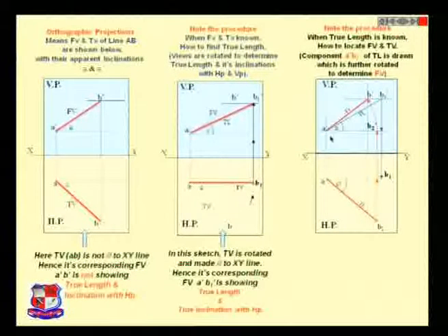Now from the true length, from this true length of the vertical plane B1 dash, I have dropped down the shadow till B1, and with AB1 as radius, A as center, mark an arc which in any case will cut the B point, which would be on the B2 parallel line itself. Join the line and you have got your top view as well as the angle of the projection of the line with the top view.